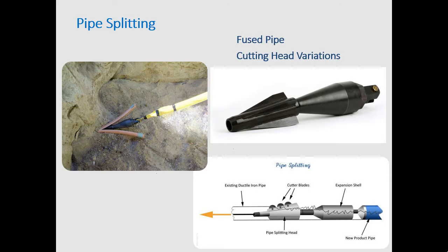And again, it's the same system, but it's splitting the pipe versus breaking and fracturing it into the ground. It's kind of just a Google search of a splitting head. This is what you're seeing in this image over here. And this pipe splitting system is a little bit larger. It's meant for splitting old ductile iron or HDPE that's larger, 8, 10, and 12 inch. These wheels actually increase in size, and they cut and split that pipe apart.